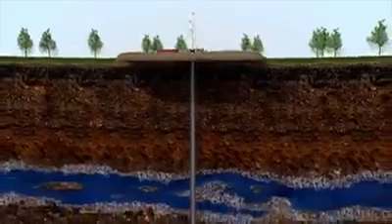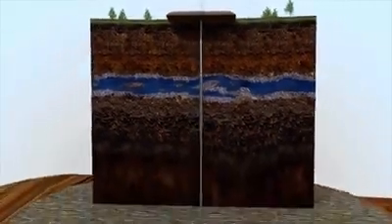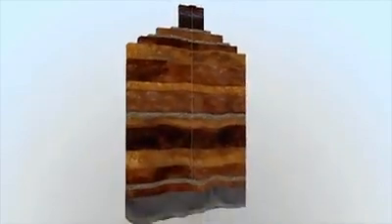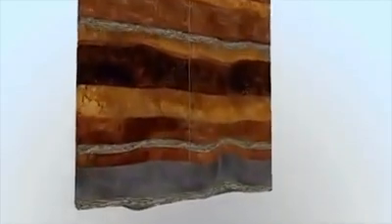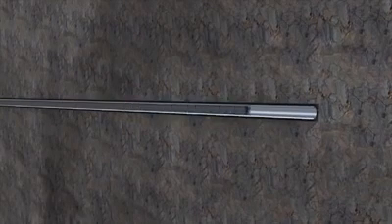What makes drilling for hydrocarbons in a shale formation unique is the necessity to drill horizontally. Vertical drilling continues to a depth called the kickoff point. This is where the wellbore begins curving to become horizontal. One of the advantages of horizontal drilling is that it's possible to drill several wells from only one drilling pad, minimizing the impact to the surface environment. When the targeted distance is reached, the drill pipe is removed, and additional steel casing is inserted through the full length of the wellbore. Once again, the casing is cemented in place.